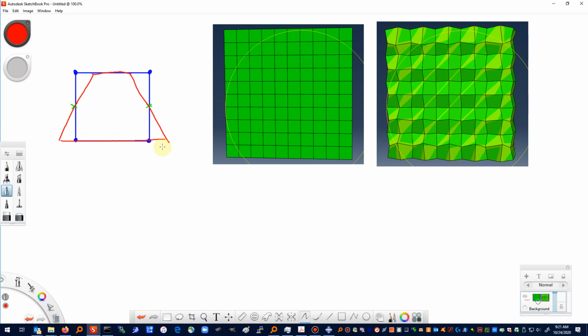And without getting into the mathematics of it, it's analogous to having a solution to an equation where there are more than one root, but only one of the roots makes physical sense, and the other root, your solver just kind of gets stuck in that spurious root. And in the case of the hourglassing, that spurious root has the same minimum energy configuration as some real root that you really want to find.